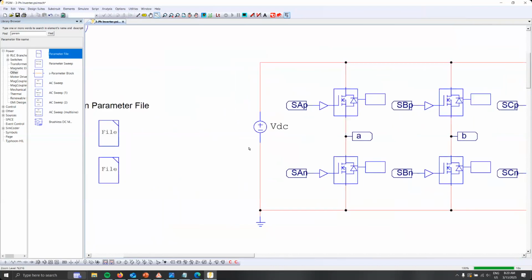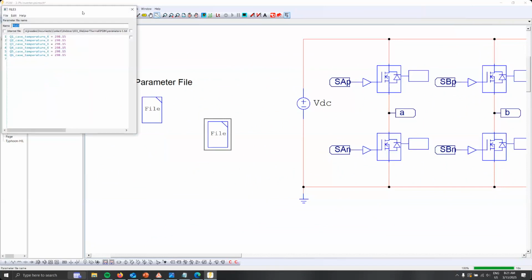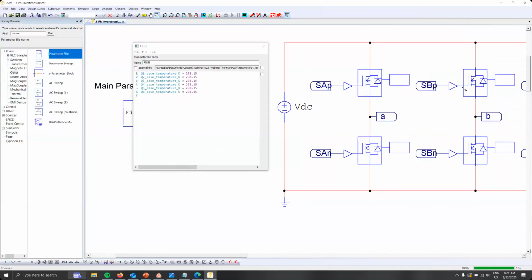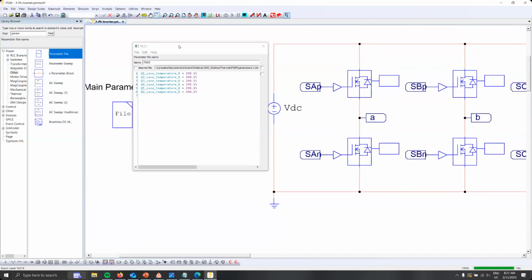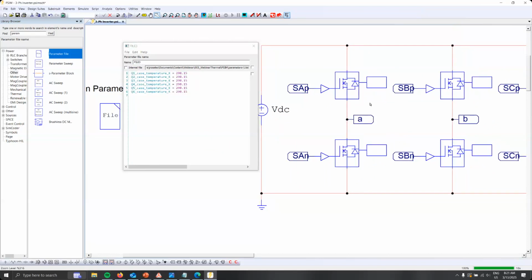Now, the initial values and all of the definitions of these variables are in this parameter file, this text file. Pretty straightforward. For the variables we're working in Kelvin, and PSIM overall works with degrees Celsius. Inside these constants, I perform the operation from Kelvin to Celsius.